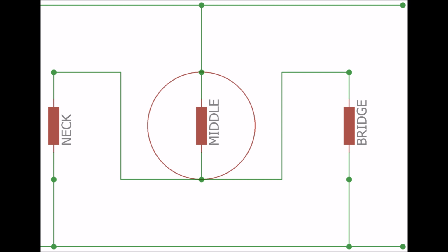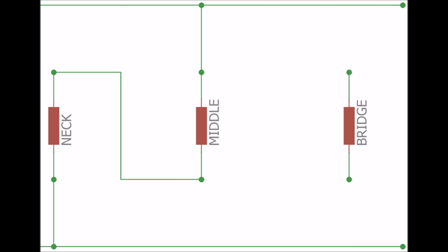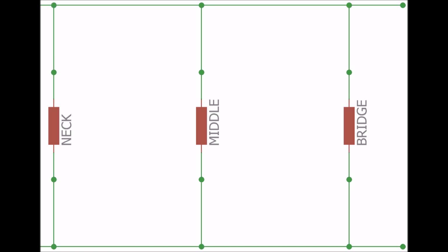If we disconnect one of the P in the PPS combination, the result is an SS combination, which solves the 2 pickup series combinations. If we reconnect the P, which we removed from the PPS combination, and connect it independently across the signal buses, we get an SSP combination. That leaves us with only the single pickup and 2 pickup parallel combinations to connect, which are components of the PPP combination, composed of the independent basic connections.